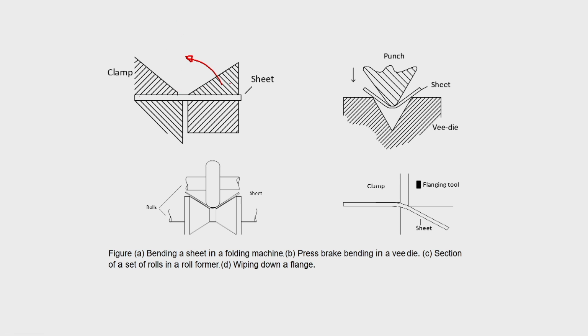Once it is rotated about an axis, this part will get bent and get the shape. But remember, it also depends upon your mechanical properties. If you are bending by 90 degrees, you may not get a 90 degree bend, because there is going to be what is called a spring back effect, because of the modulus of elasticity. So you have to do a little bit of trial and error and find out how much it has to be bent, but by this machine it becomes very simple.